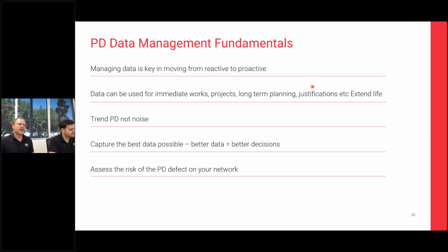So you may need to bring that forward because of the condition data that you're capturing here, and you can justify that because all the condition data is within your database. Now, another important thing is to trend PD data, not noise.